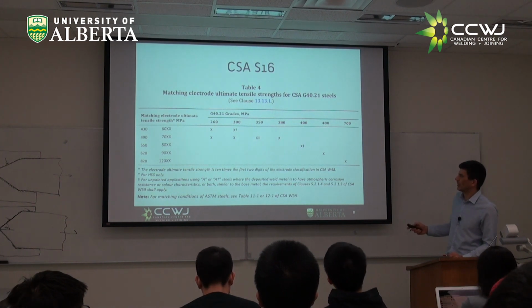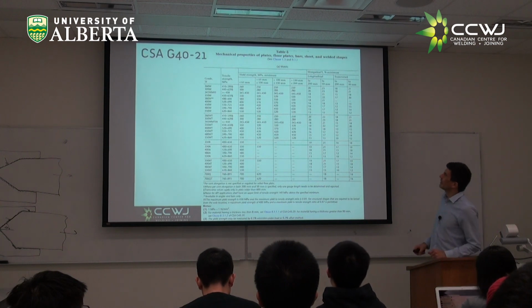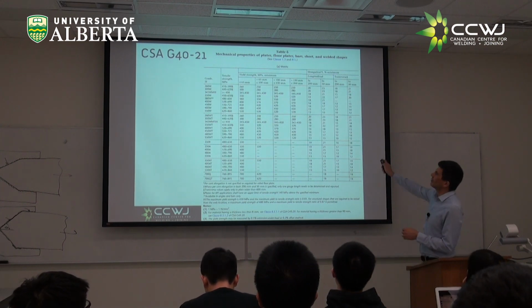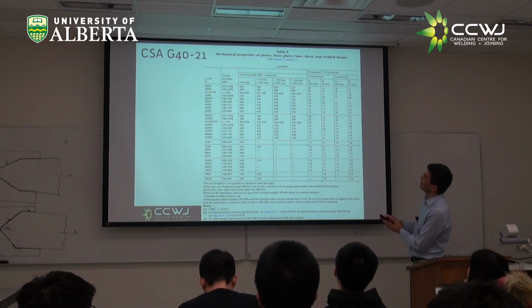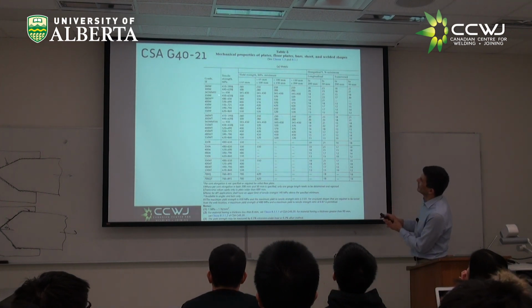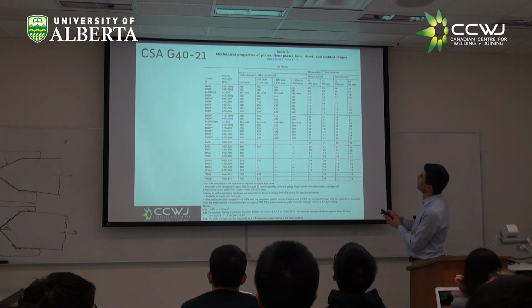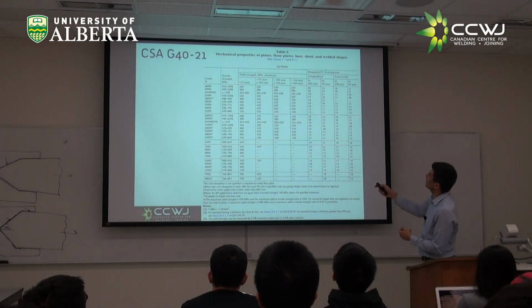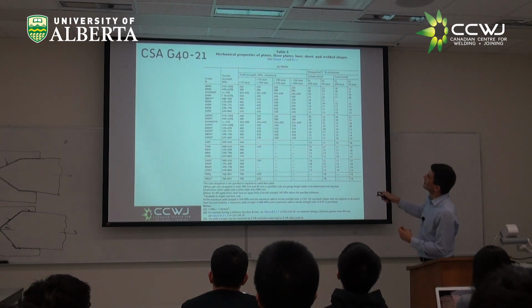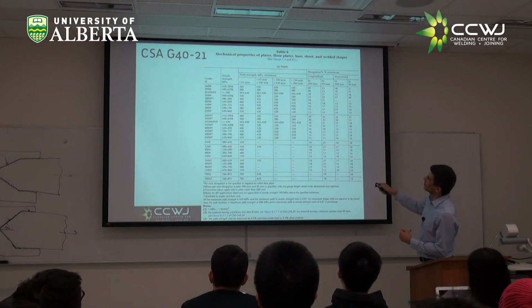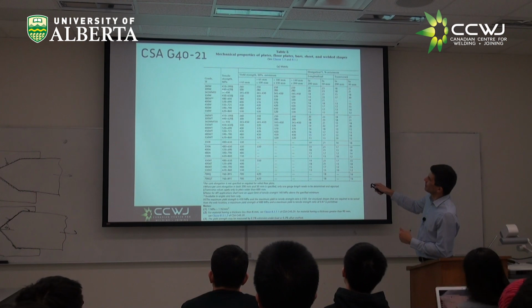And you will have this in your formula sheet. Here, you have the relationship between the yield strength, right, and the UTS. So look, this is what Mitch said. Yield strength minimum, right? A 300W should be 300 typically, right? A 350 should be 350, right? But could be more. That's what the standard says. This is the yield strength. But now we have the tensile strength here. Look, the one that the 300 that should be 300 actually is 440.